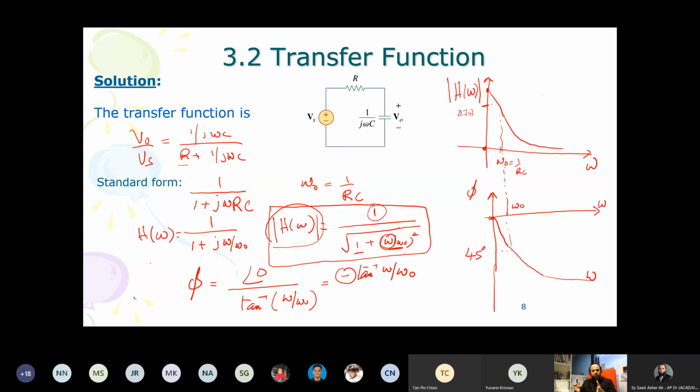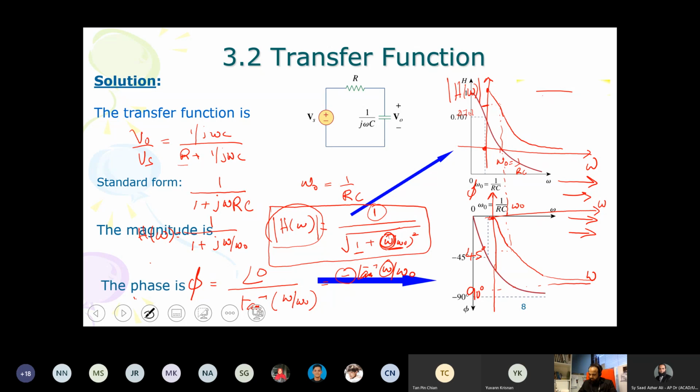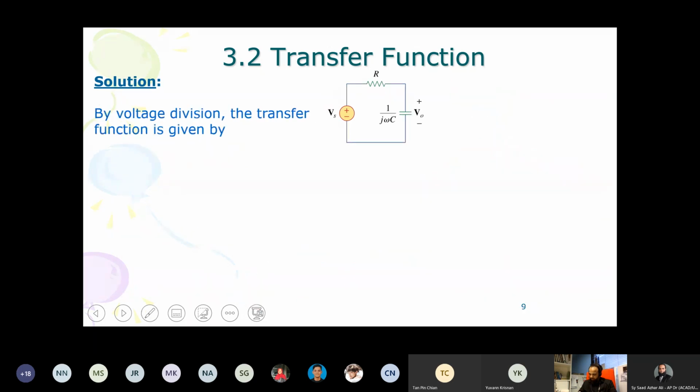By the way, don't worry about how we are doing it. It's just putting the value in this omega and finding numerically. So this is the very basic way to find the frequency response, that we put omega, but practically it is impossible because we are trying to go for infinity. At infinity, remember tan inverse of infinity is 90. So the maximum it will go will be until 90. Let me sum it up in a way, magnitude, phase. I'll be showing it here.